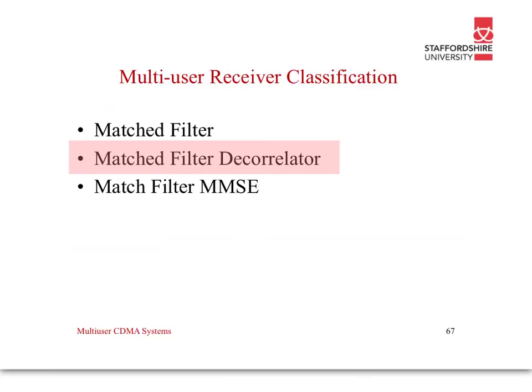So at the receiver, we look to see which symbol our received signal is closest to. We perform a correlation of what we've received with each of the 4 symbols, if it's QPSK, for instance, and wherever the correlation is highest, that is the one that was sent.